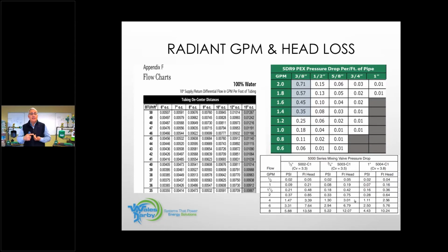We're putting in the glass, heat above, heat below, just like we did in the beginning. And it would give you all this information. And if you're using a mixed valve, you would click on that to add the mixed valve. You put the size in. There's your GPM. There's your head. There's your water temperature. All right.